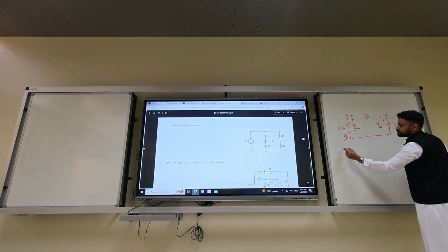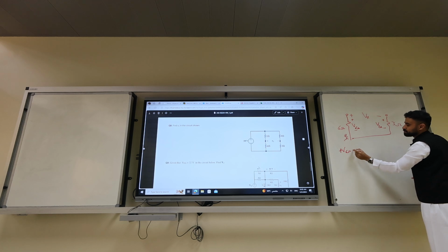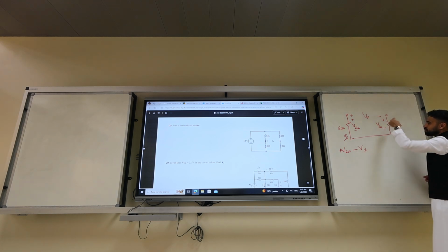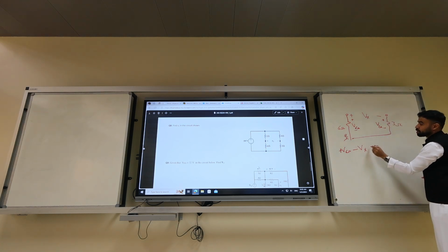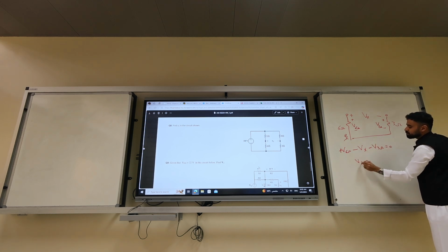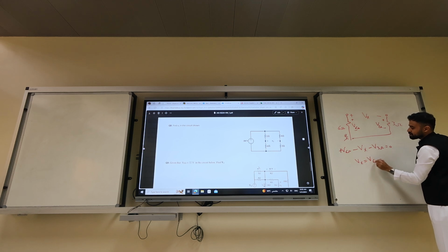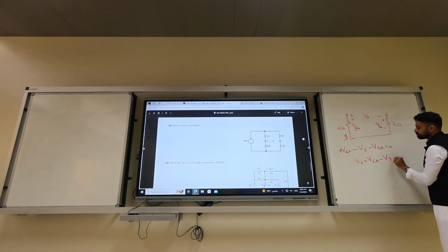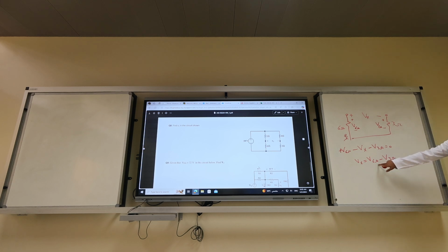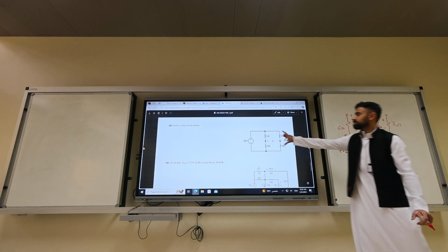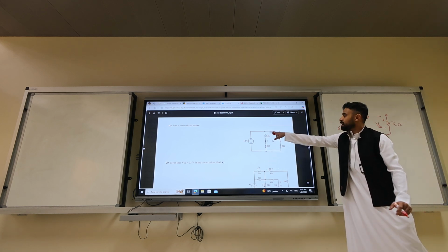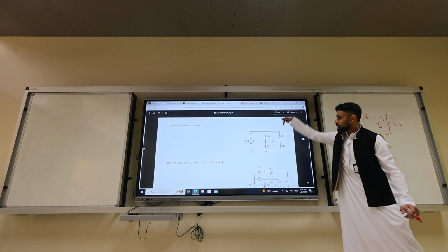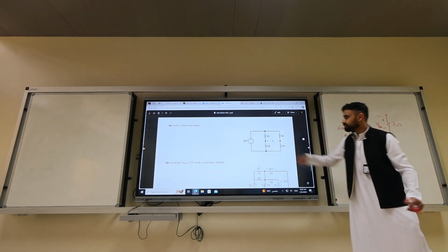Voltage rise or voltage drop? Drop. So Vx equals V6 ohm minus V3 ohm. How to get V6 ohm? We'll study it today, that you can calculate the current here. How to get V3? You can calculate the current that goes from top to bottom.